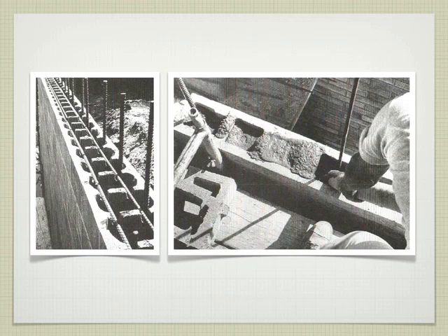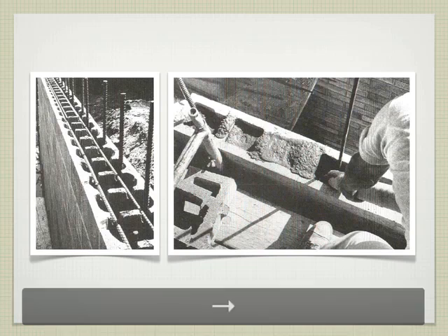Likewise, these dowels are coming up from underneath, tied into the footing. So this is a much better example of how we would do it here in the state of California, subject to earthquake loads. After we have this reinforcing in and we've built our wall up, we can fill the wall with concrete, and it's becoming kind of a hybrid of a concrete masonry unit wall and an actual concrete wall. Our reinforcing can help support larger structural loads. So it's a pretty good economical way of building a wall that isn't entirely concrete but has a lot of the strength of a concrete wall. It's that internal hybrid strategy.